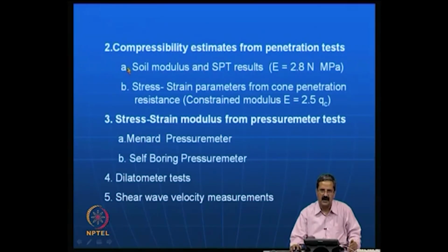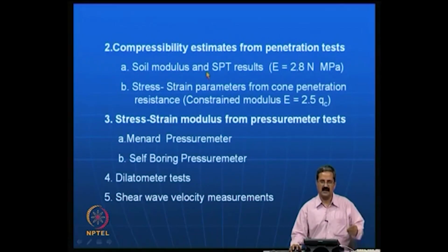Settlements are very important. If you want to measure settlements, you need proper instrumentation, and you also need to estimate settlements. For example, you have an SPT value N, say 10. If you want to use a modulus in any finite element calculations, you need to have these parameters for analysis. Once you do an SPT or CPT test, how you use that in analysis and design is very important.